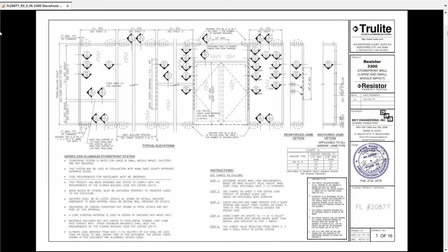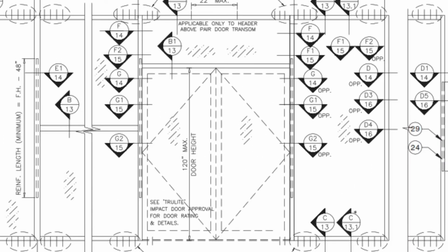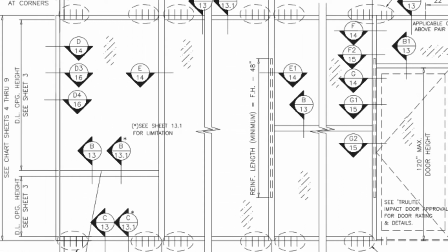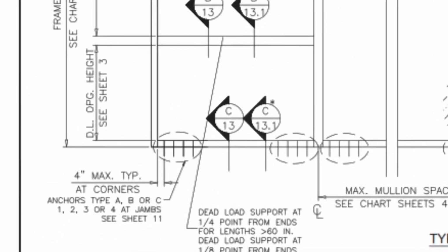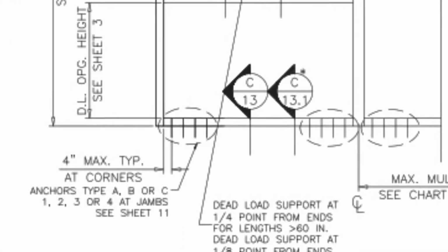So this perspective is standing and looking at something. And you can see this drawing shows a pair of doors in the middle. They have little sideways slashes to indicate that there's supposed to be glass there. And then you have some vertical elements, and then you have horizontal elements. Looks like window framing. That's what it's intended to represent. And you have these clusters of screw fasteners, little lines, 4 lines with a circle around them.